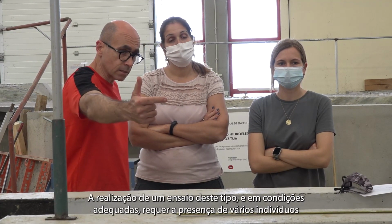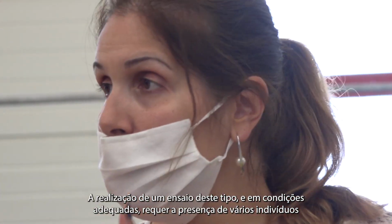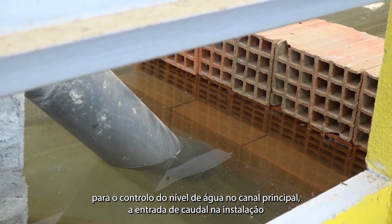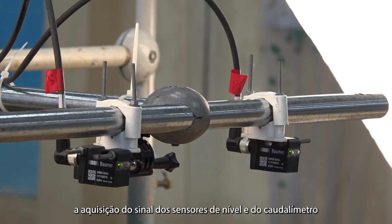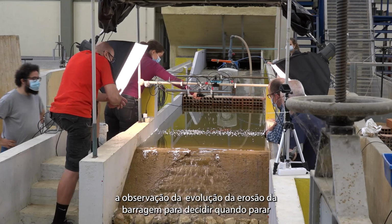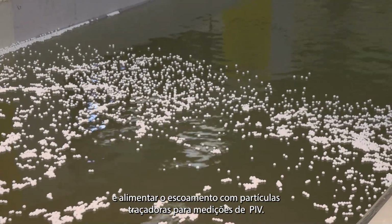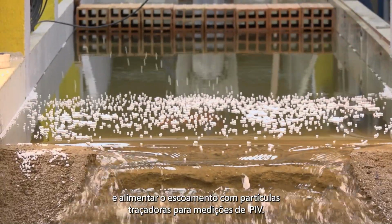An experimental test of this kind, and under these conditions, requires the presence of several individuals to control the water level in the main channel, the water inlet to the facility, the signal acquisition of the level probes and flow meter, the evolution of the dam erosion, to decide when to stop and acquire depth images, and to feed the flow with seeding particles for PIV measurements.